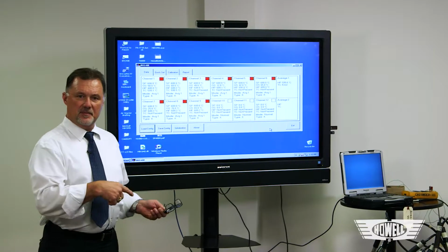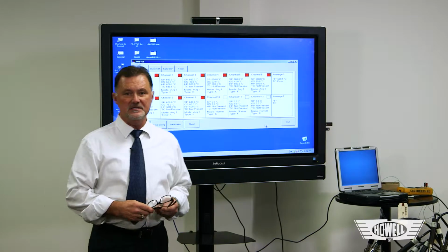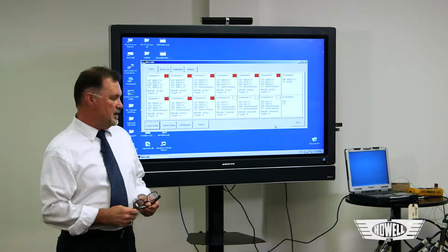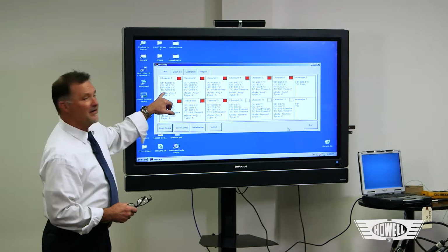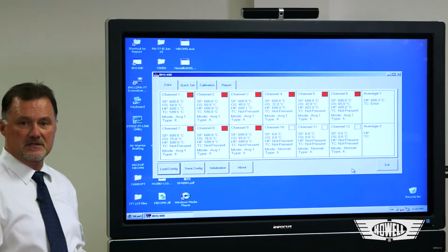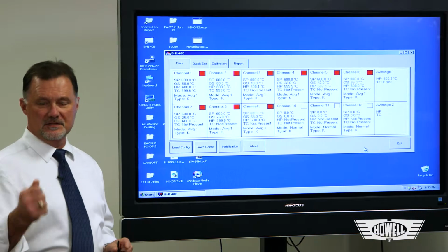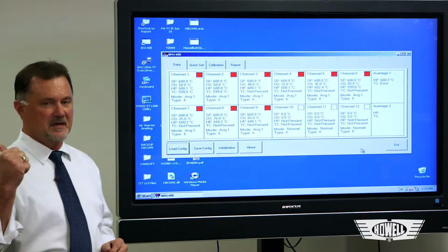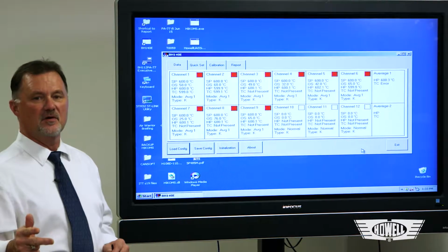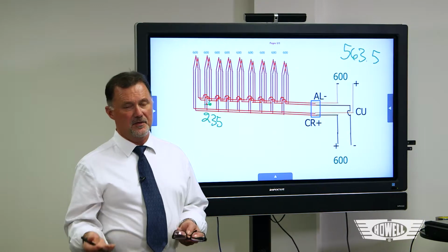Okay, so we've put the apparatus back the way we had it, and we've now removed the alumel lead that goes to the TIT indicator for thermocouple number 7 in this half harness. As you can see here, I'm at 599.4. So basically unchanged. We've got an open, no impact. So once again, review. Sometimes the overall average will go up with an open, sometimes it'll go down, sometimes there's no effect.